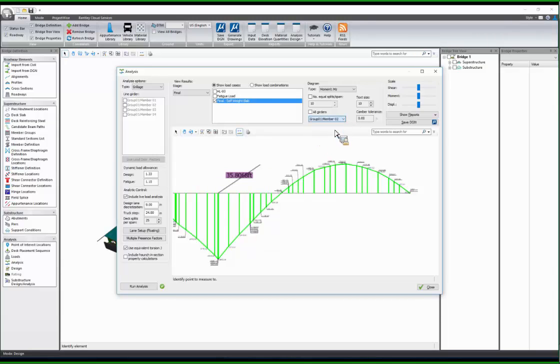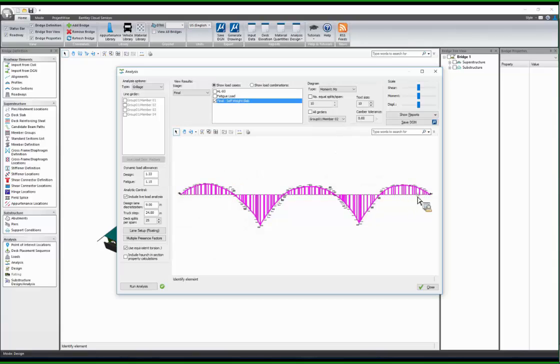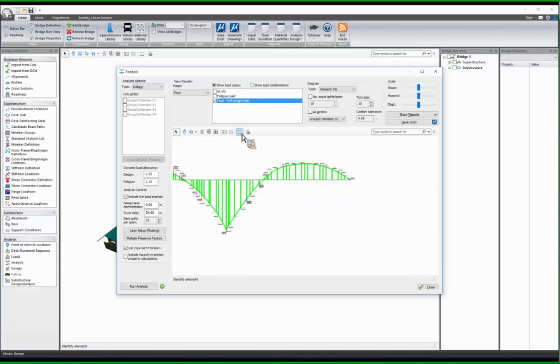If you are working on a different member, the same thing, look, very quick. You can go back in here. This is what I want in that location, and then move it there. This is 41, you see. Remember, that bridge is not even parallel. There's a skew, but that is the location where that particular inflection point is for that particular girder in that span. So that's how I will use it.